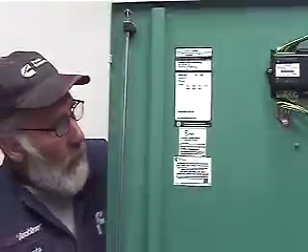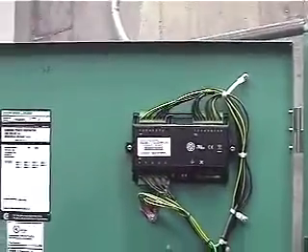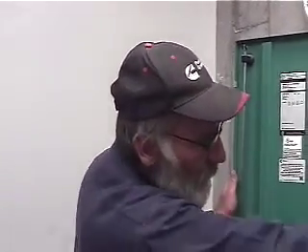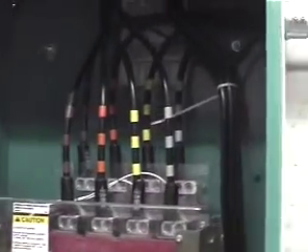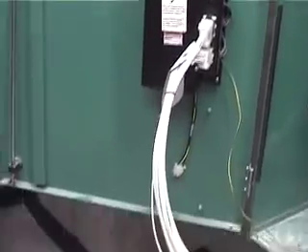It's not always recommended, because when you pull those off, on these green terminals here you do have live 480. I'm assuming we're 480. You have live 480 sitting on 3 of those terminals because of the wires coming from, see those white wires back there? Those white wires end up coming into this harness here, come up here and go into here. So with that being said, caution.